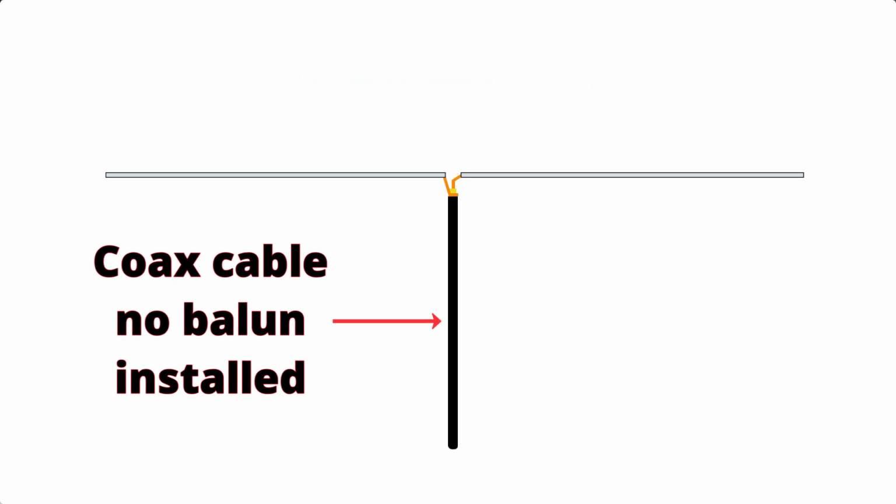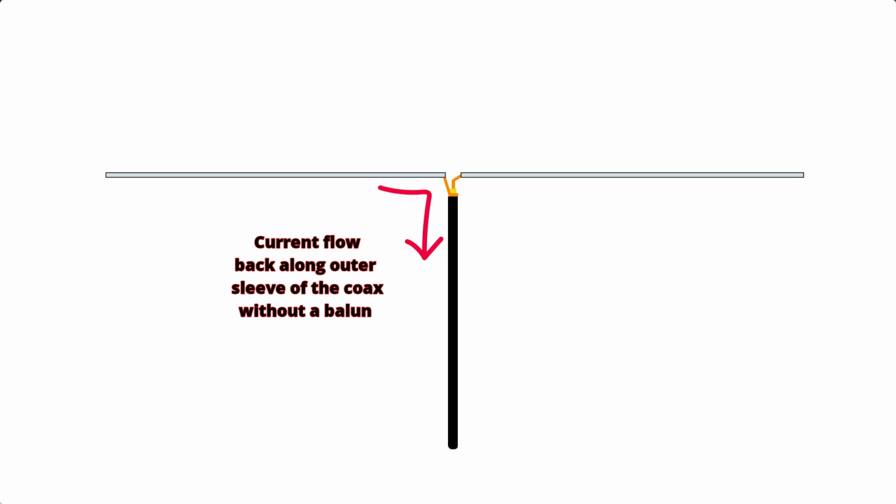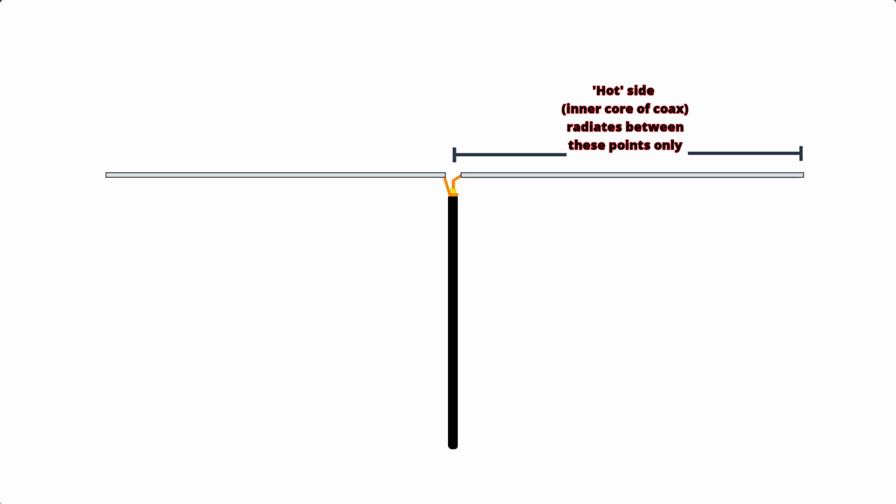The second point is that if you've got this horizontal dipole configured in this way, you've still got radiating elements. It's not all horizontally polarized, you've got some vertical aspect to it as well. And it might be the other way around. If you've got a center fed dipole that's vertical and you've got the coax coming off without a balun in place, you've got some horizontal radiation there. Apart from interference that it could cause and high levels of RF in the shack and things like that, it's not going to be too detrimental.